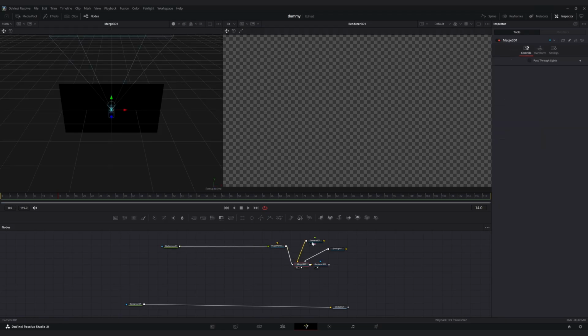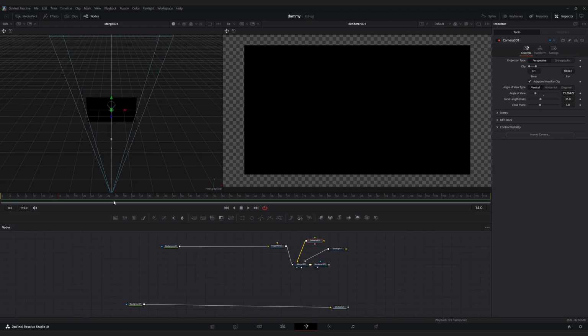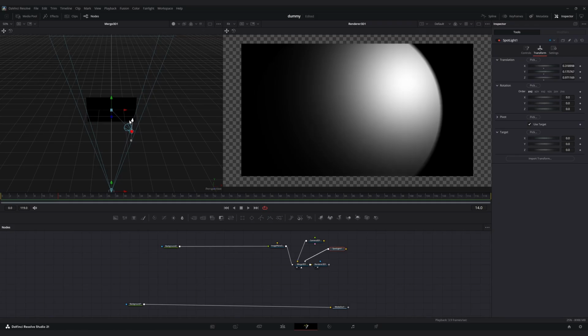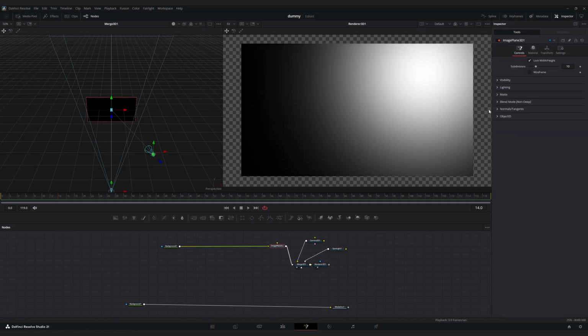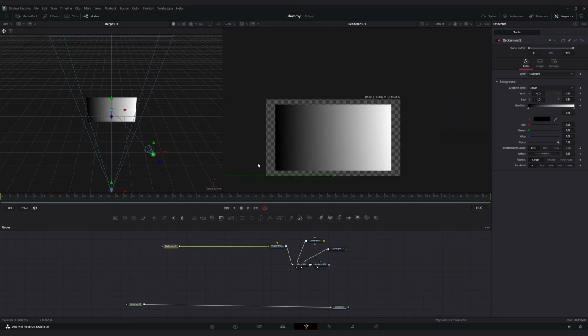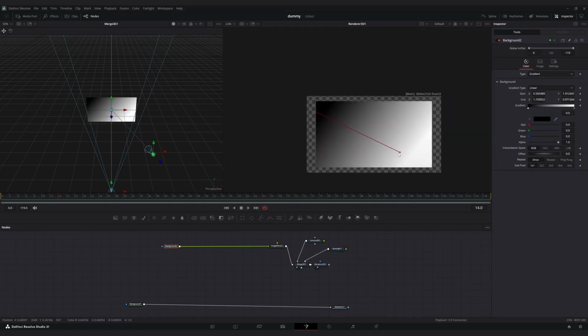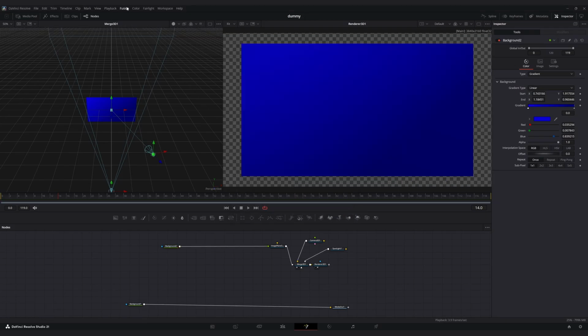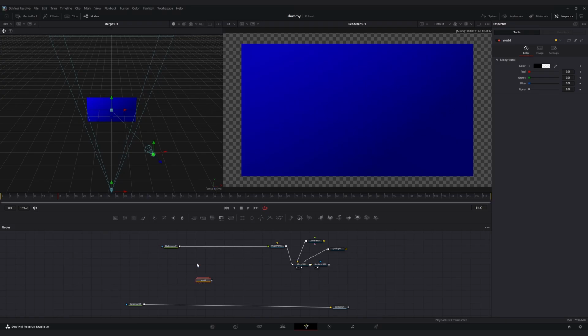Zoom out the camera so the plane can come into focus. Adjust the spotlight and set use target checkbox and remove the reflection from the specular intensity. Set background to gradient and adjust the blue colors. Now I will add the map from Fusion, Import and SVG. Set to 8K because we need more details here. Merge the map after the blue background.